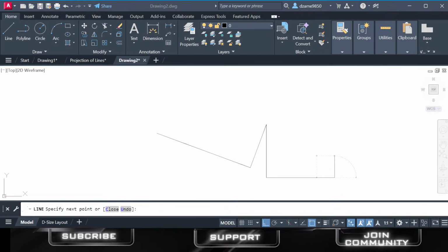Okay. Further, this is very important. Pay attention to this. This is where we have various items. Before here, let me just talk about this cube. That's what you call a ViewCube. On the right side here, you'll see the cube, which helps you to navigate in between 3D and also 2D. And it's good especially for 3D because you're able to navigate and see. You can click here to change views in the actual drawing, to the front side, etc. For example, this line, if it's active, you click, you change, and you're able to navigate.